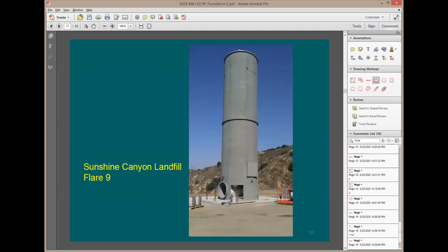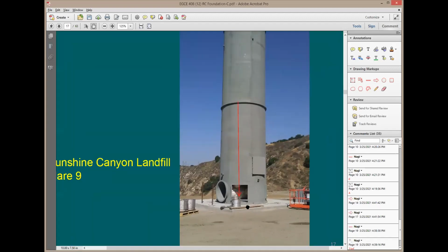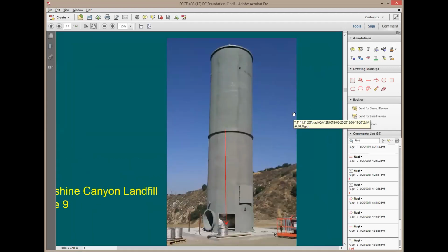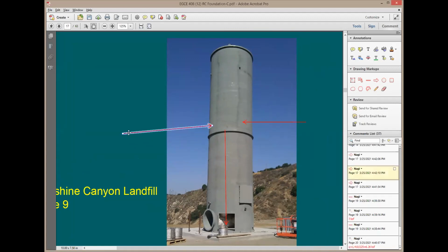We're going to say yes, total load is going to be coming downwards like this, right? But in this structure here, if you have an earthquake, the earthquake is going to generate horizontal load, like here, for example, some load like this. Or it could also be in this direction, because it depends on the earthquake direction, right? And if the earthquake load is coming this way, then taking this horizontal load applied at this height, it's going to generate some moment on this footing along with this applied vertical load. So in this case, this footing here is designed for vertical load and moment.